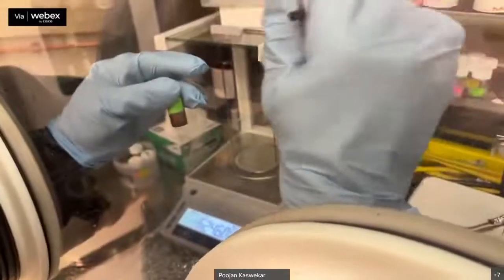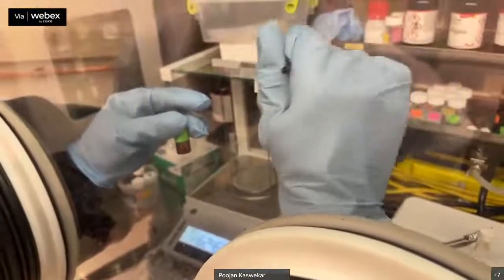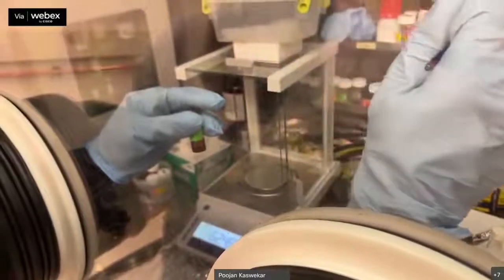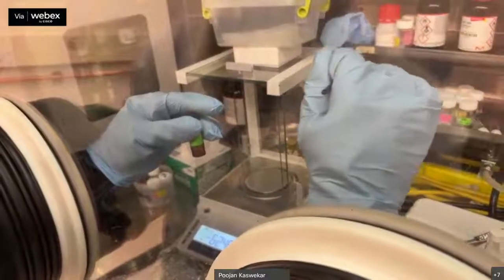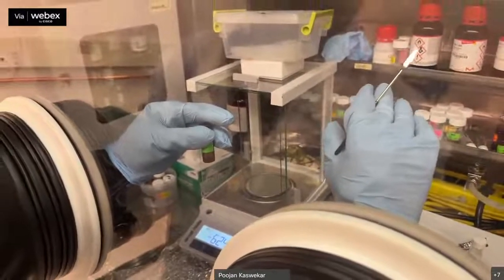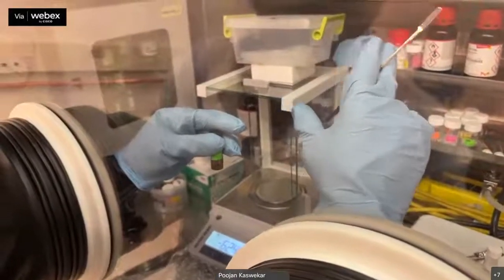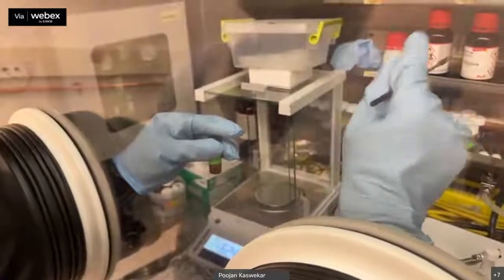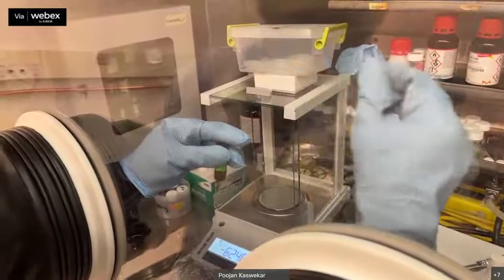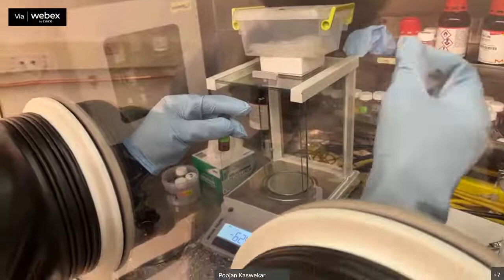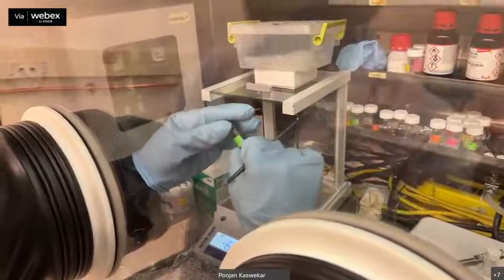So to add to Dr. Mukesh, for the chemical process in the glove box too, we have different modes. We have a purging mode and a circulation mode. Circulation mode will circulate whatever atmosphere is inside the glove box. In purging mode, it will just take away the old nitrogen and get new nitrogen into the glove box. We are using 180 liter liquid nitrogen cylinders to purge the nitrogen into the glove box. For some materials, you need the circulation mode, and for other materials which will accumulate solvents or something, you need to purge while fabricating. So those are the two modes available in this glove box.